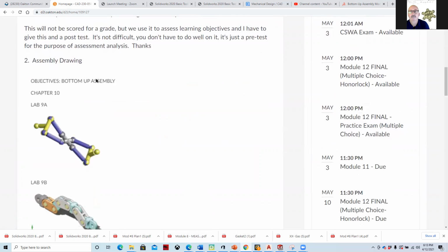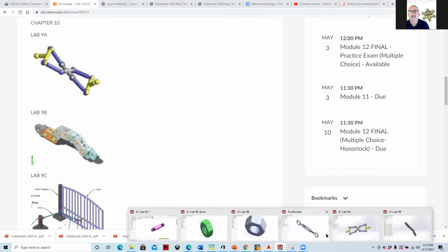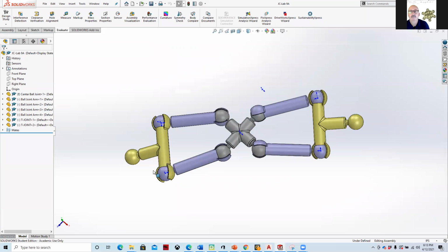And then as we go into these assemblies and assembly modeling, this is really what's great about SolidWorks, because you have the ability to create these assemblies and then work with what's called mates. And mates are what constrain the degrees of freedom in a SolidWorks model. So if we take a look at some of the assemblies, here's this one right here. And what we have is these different mates with these concentric mates. If you hover over a mate, it will show you where that's at.